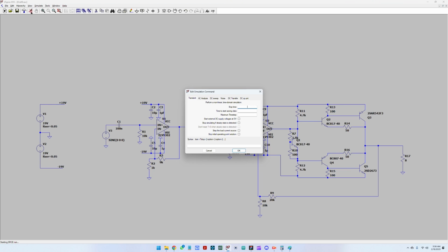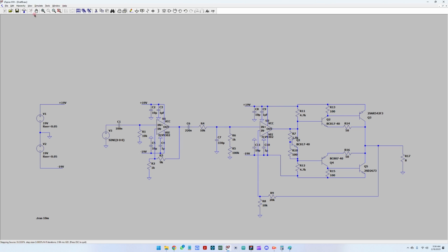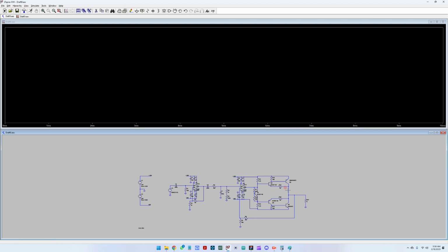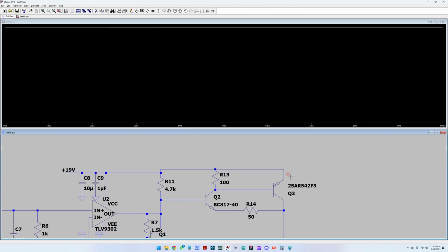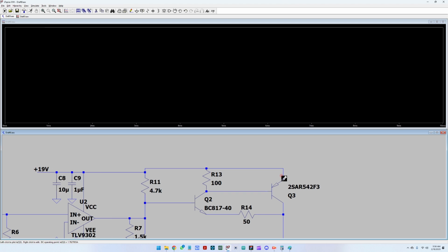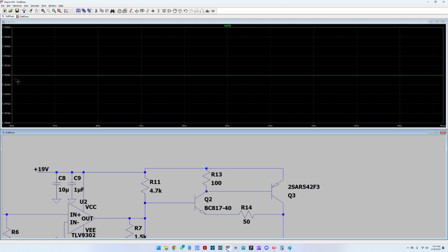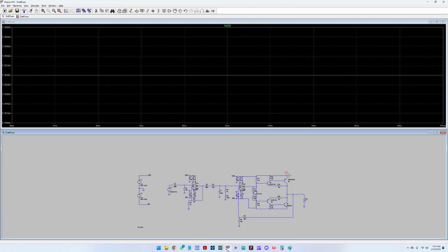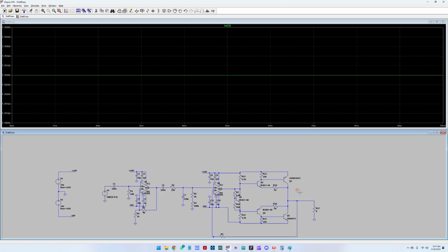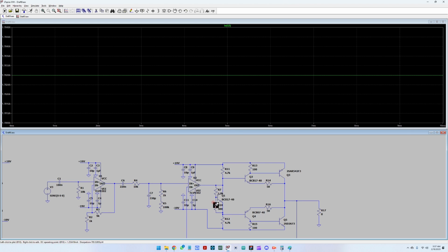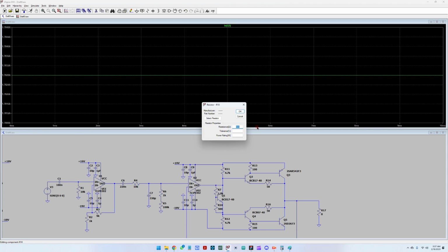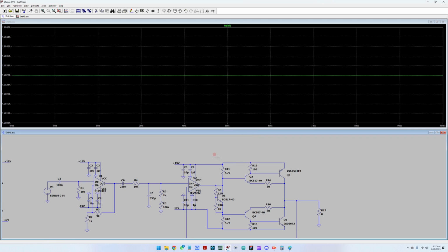Let's create a 10 millisecond simulation here, so 10 milliseconds, and run the simulation. And let us look here on this pin. Okay, ooh, 1.7 amps. 1.7 is quite much. Let us replace this with 1.1 kilo. First, let's start with 1 kilo ohm.